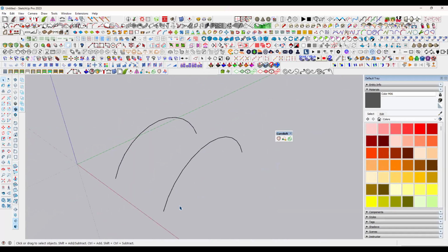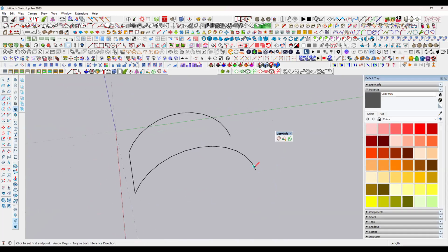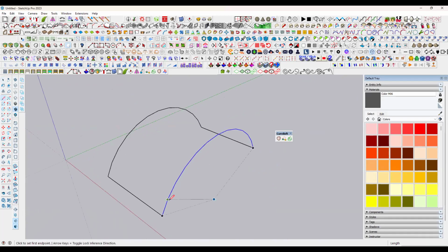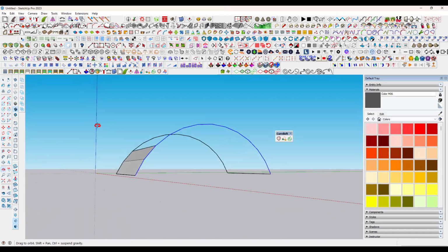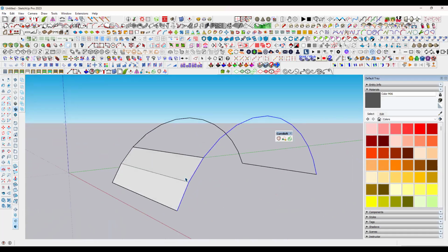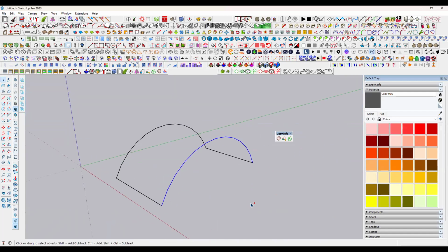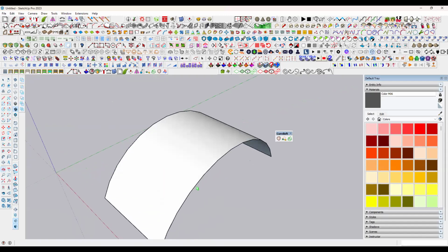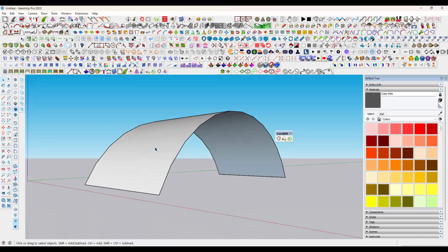Generally, without this one, if you want to create that, we have to draw the line maybe by using this. And I'm taking one more line maybe from here to here. And how is it closing the surface? No. Again, we have to draw the line maybe from here to here and a line from here to here. But still, you are not getting a smooth surface. See, it is not giving the proper shape. Now, with the help of this one, I can directly click. Sorry, first, while creating these things, don't create a closure loop for this. Now I'm selecting both the lines and applying that. See, it is creating a proper surface. And it is creating a smooth surface also.